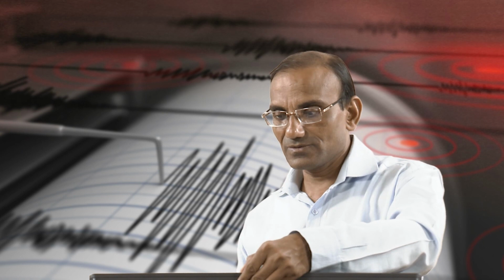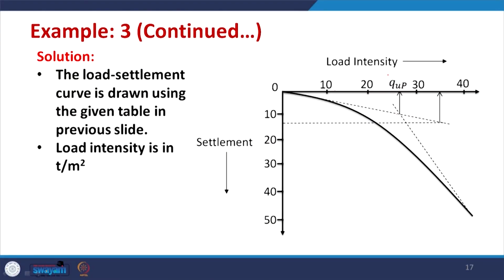Now, for this 12.8 mm settlement, we determine the load intensity using the method suggested by researchers. In this case, you use this chart again, and in this chart you look for 12.8 mm settlement. Here we cannot use this, because this is out. For 12.8 mm, your curve is out. So, you use this asymptotic tangent, and this is a method suggested by Rao and Ramaswamy.